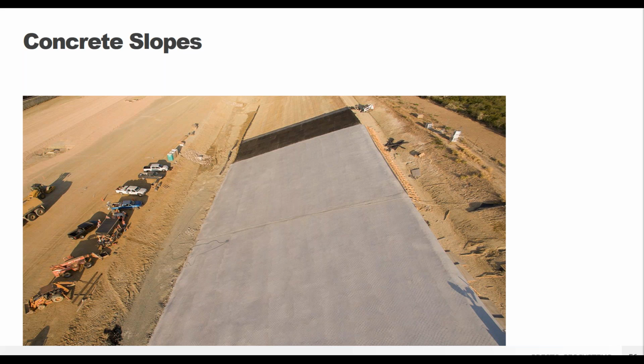And pore water pressure buildup is always a concern underneath concrete structures. So we typically will recommend either some sort of drainage pipe be included, or drilling weep holes through the set concrete to help relieve that pressure so that you don't get failure under the scenario. Either one, totally able to be integrated into the GeoWeb system, no concerns there.